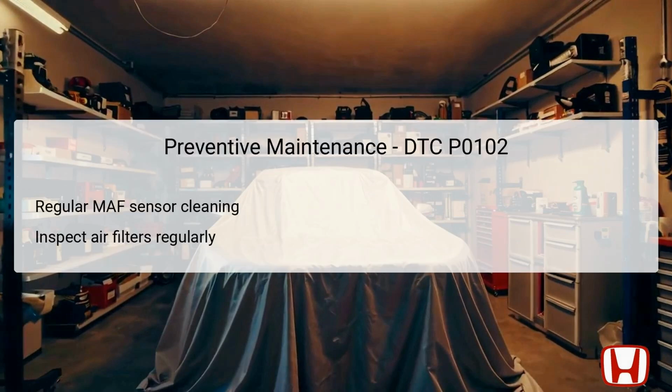To prevent future occurrences of DTC P0102, regular maintenance of the mass airflow sensor and associated systems is advisable. Periodically cleaning the MAF sensor can help maintain its accuracy. Use specialized MAF sensor cleaner to avoid damaging the sensitive components.